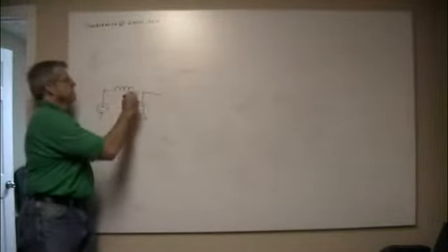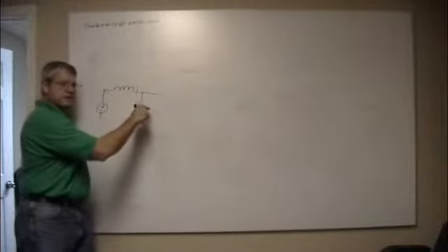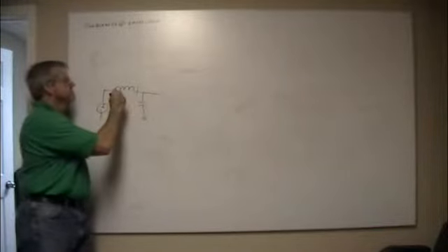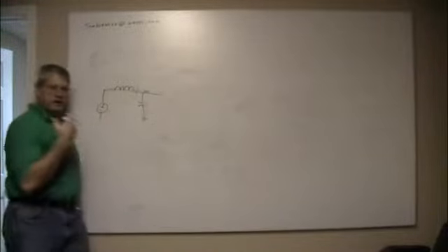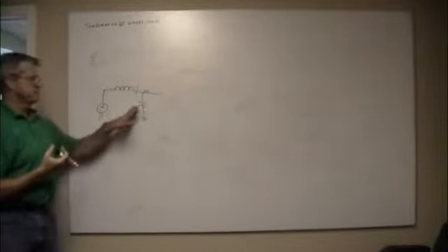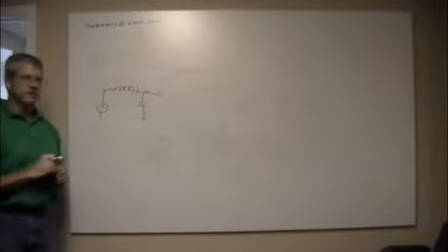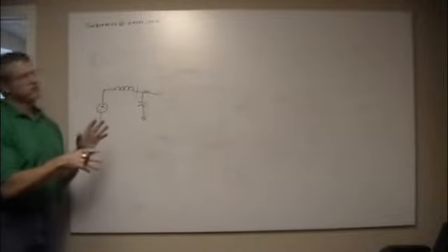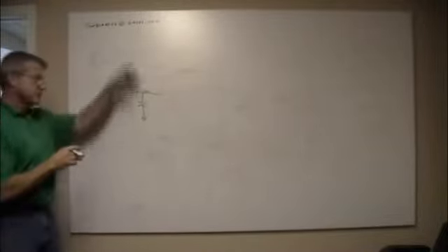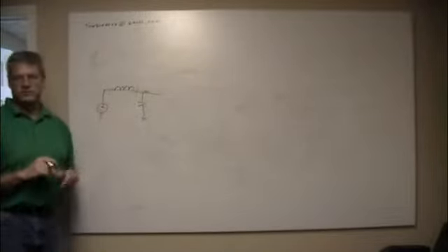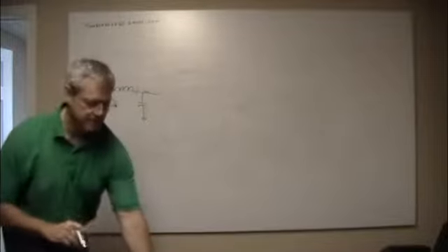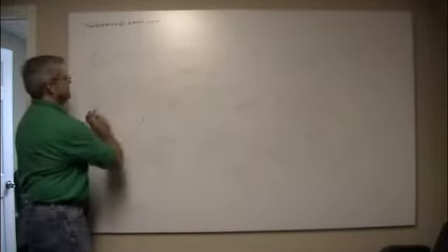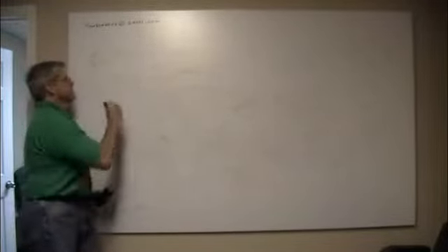By putting this here, this basically blocks that AC signal, right? Because inductors like to have DC. They are current memory, whereas a capacitor is voltage memory. So you get a certain amount of current through it, it wants to keep it there. When you change it suddenly, the voltage will change a lot, but the current won't. We did that with some graphs last week, if I remember right. I'll repeat that again, just for completeness.